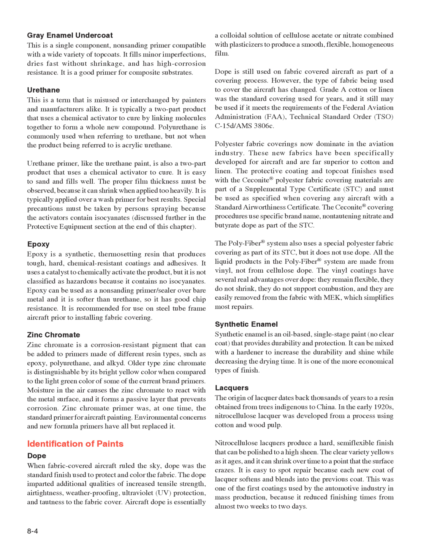Epoxy. Epoxy is a synthetic, thermosetting resin that produces tough, hard, chemical-resistant coatings and adhesives. It uses a catalyst to chemically activate the product, but it is not classified as hazardous because it contains no isocyanates. Epoxy can be used as a non-sanding primer/sealer over bare metal, and it is softer than urethane, so it has good chip resistance. It is recommended for use on steel tube frame aircraft prior to installing fabric covering.